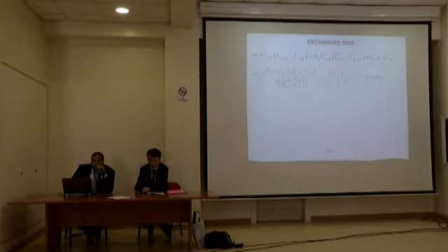The ambient temperature is set at 20 degrees Celsius and the air to fuel ratio to 15, which is approximately stoichiometric combustion. And in each geometry, 3 configurations were tested. First geometry, the inner diameter was fixed and the outer diameter varied from a ratio of 1.25 to 1.75.